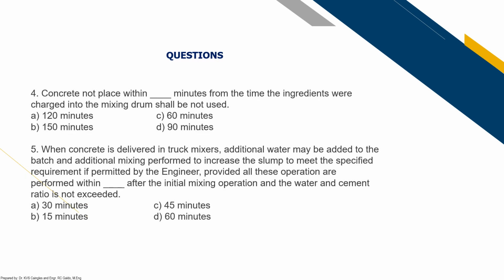So just search them. Usually you can find it in the DPWH blue book. It is common, and it is about concrete. If you search the DPWH blue book or standard specification, you will find the answers usually in Item 405, or the structural concrete item of works. You can find it there, or you can also search on Google.